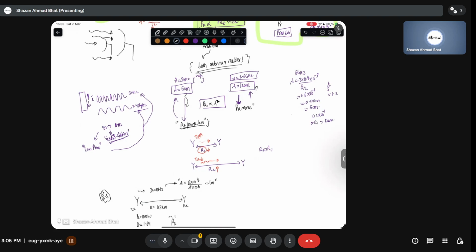It's not the radiated power, I'm again mentioning the point. In this case, the received power at 5 gigahertz will be less compared to that of 2.4 gigahertz. And why is it the case that the received power is dropping as the wavelength is reducing? Because if the wavelength is reducing, the frequency is increasing and the attenuation actually increases.